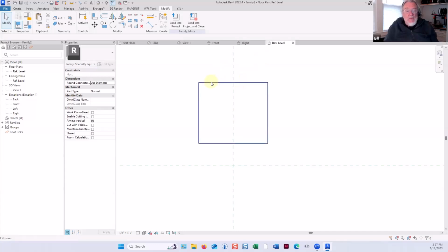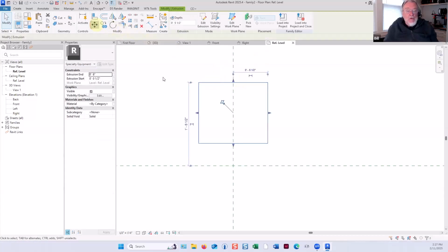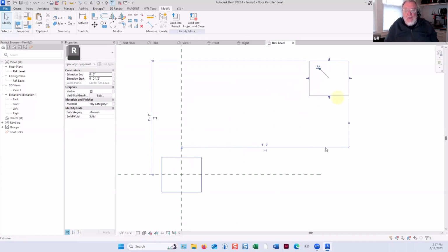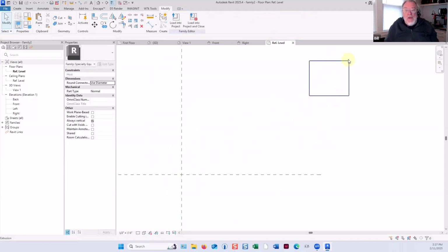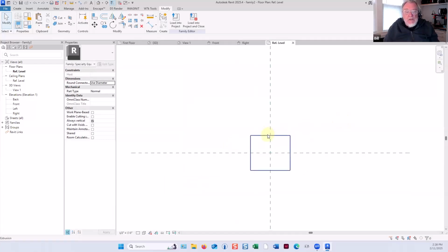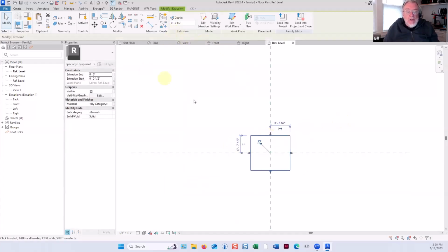So it clicks on the line, and then we pick this again, move, go from the midpoint of here down to the line. If I'd made this family with the thing over there, I'd be placing it, my cursor would be here, and the thing would be, you know, 3 feet off in the other direction. Okay, so here's this, it's the right height.